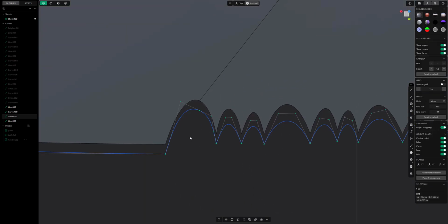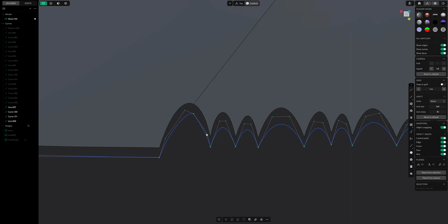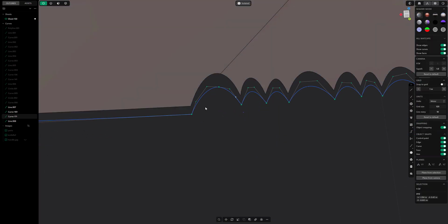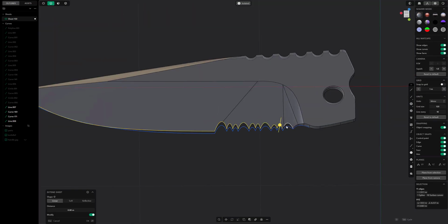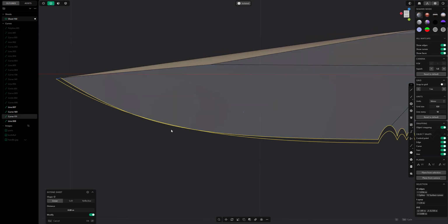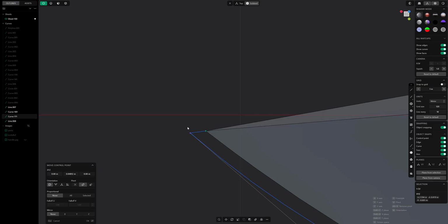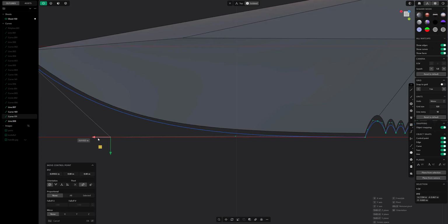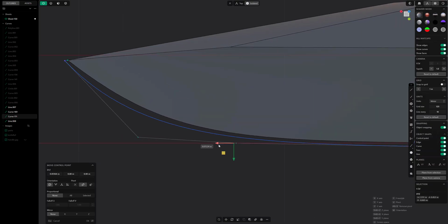The cool part here is that you don't even have to put in-betweens at the point of each of these teeth. Like when we loft this using a G0, it's simply just going to go straight down. So I don't even have to put anything in between. It's kind of crazy. So then select. This doesn't line up very good, so I'm going to go ahead and adjust this curve a little bit just to make sure that I have about equal distance here. So I'm looking to see how thick this is looking from the main body. I'm just trying to have something consistent.